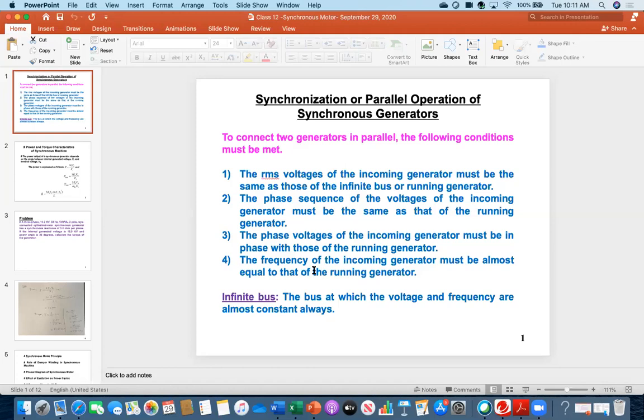The same thing applies not only to the hair dryer but to any device: you have 60 hertz and their system is different. Again, you will face the same problem. Also, here the voltage is 120 volt, or we say 115 volt, but in Europe and Asian countries their voltage is 220 or 230. The same thing, voltage is also not matching. Therefore, for example, if you want to charge your cell phone, you must have an internationally adapted converter. Otherwise, you cannot plug into their system because your voltage is 120 and theirs is 220. Again, immediately it will be burnt off.